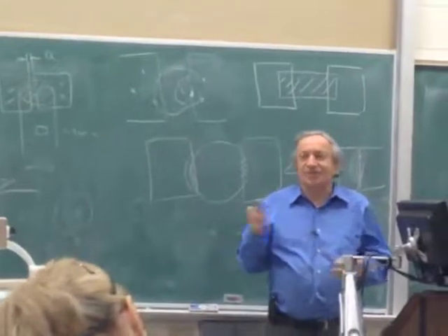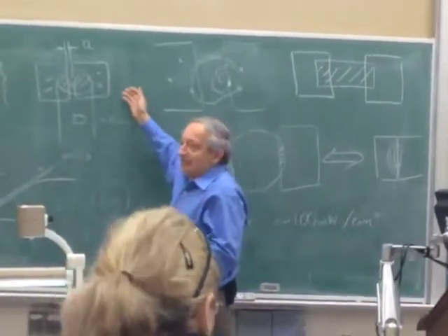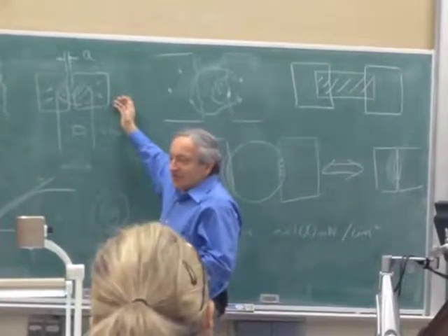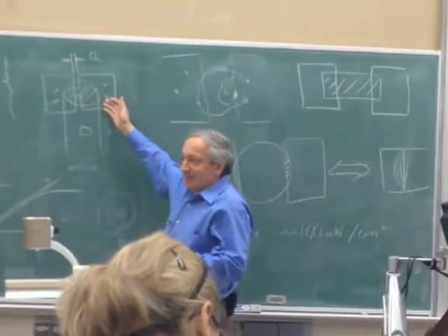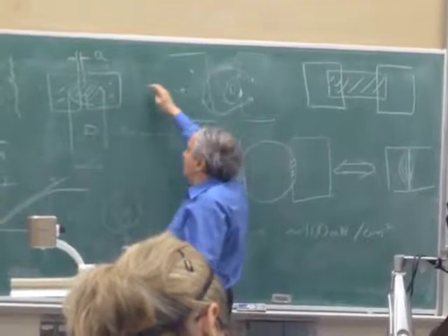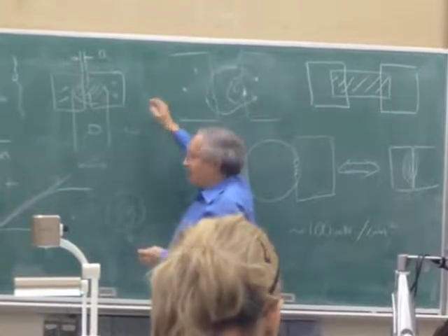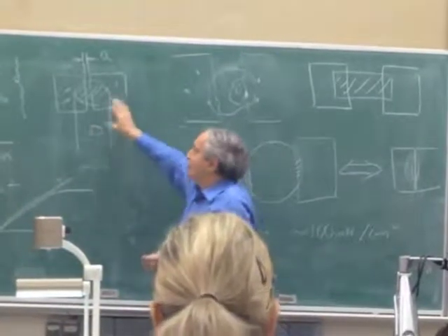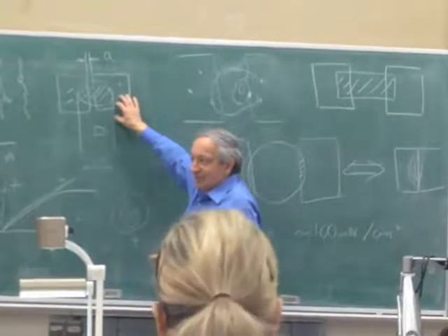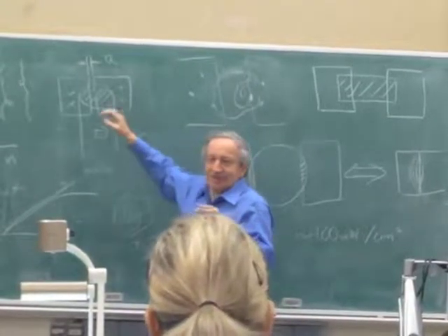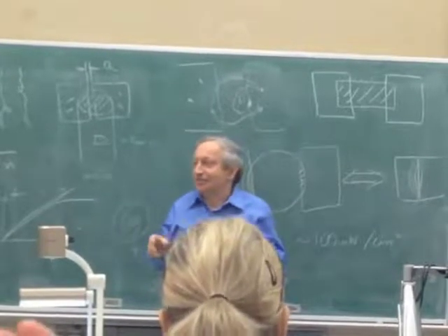Because you know that these detectors convert light to current, not light to voltage. So it's incorrect to use them in voltage mode in a design, because the voltage will reach 0.7 volts and saturate very quickly. But the current will keep going up until it saturates. So what you really use is the current mode, not voltage mode. Is that clear to everybody what I mean by current mode? You use it as a current source, not as a voltage source.